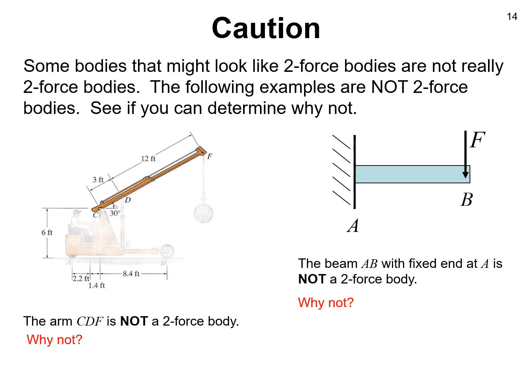And in the right-hand object, I have A and B. You might say, wait a minute, that is a two-force body because I see only 2 points where something is touching it. There's 1 point of contact at A, 1 point of contact at B. Isn't that a two-force body? Think a bit more carefully about what reaction type you see at point A, and that might give you a clue.